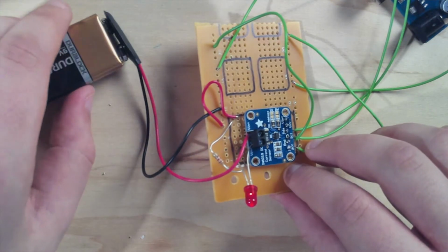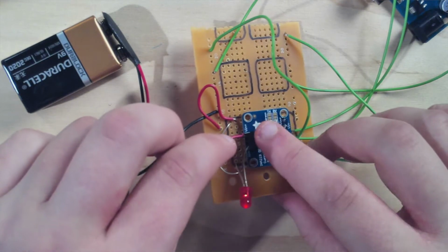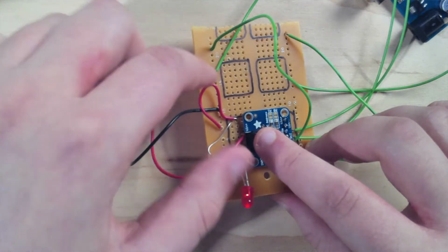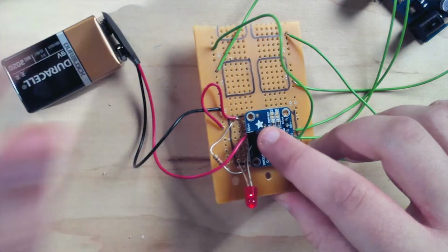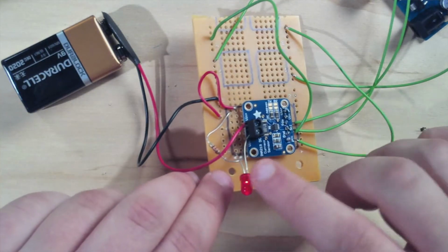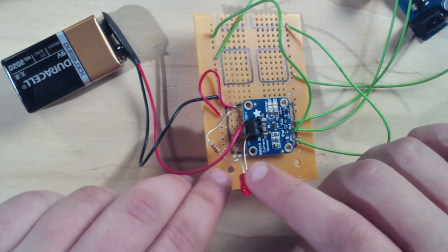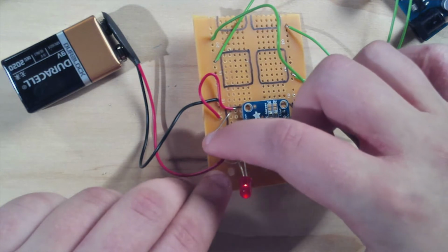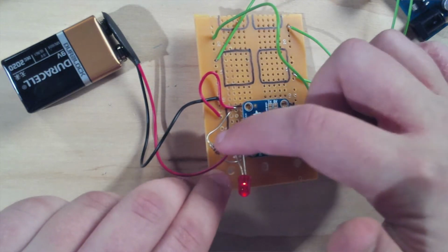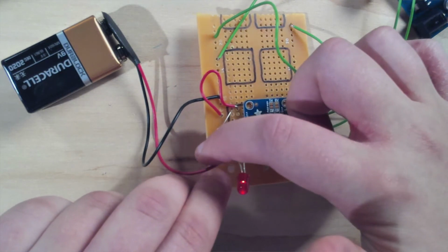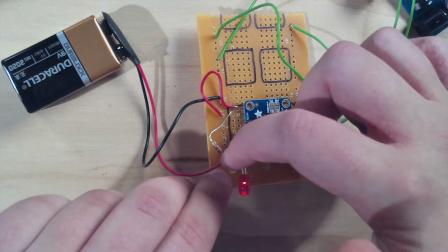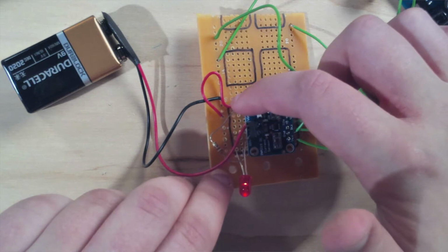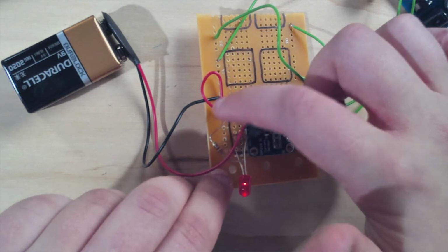We have the 9-volt battery with the positive going into the V in positive on the current sensor and the negative for ground to the ground here. Our simple series circuit, the longer part of the LED goes into the V minus here, and we have a 200 ohm, or in my case a 220 ohm resistor touching the smaller piece of the LED and put it into a pin that will then go to ground.